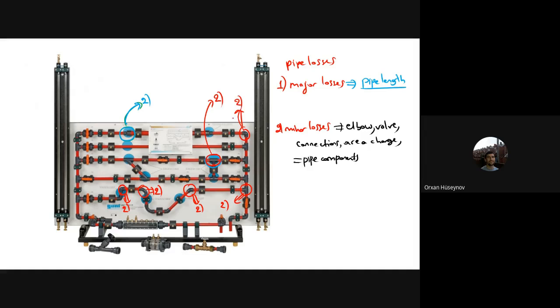But there are lots of minor losses. Okay, but you shouldn't take the name literally as minor. It can sometimes be major. So what it means is that the name is minor loss, but sometimes it is possible that 100% of the losses is due to minor losses. Okay, but minor doesn't mean that it will always be minor. It is just a name. Okay, nomenclature. And here you can see the valves. These are all valves, and these are all minor losses. Now comes the major loss.